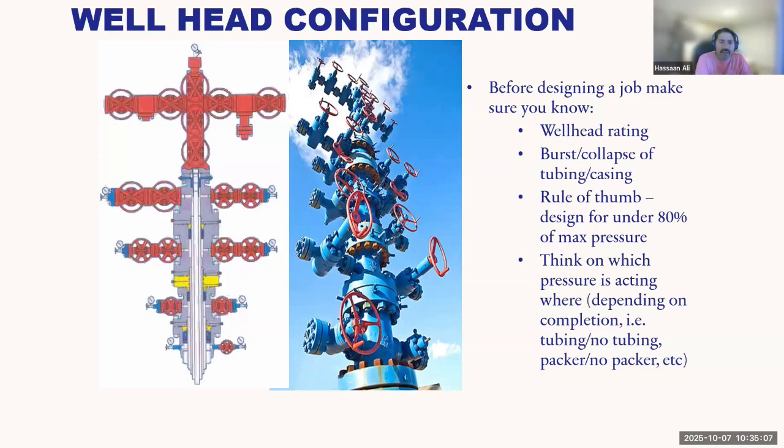So think of the wellhead as a means of production. It is right there on the surface. Some people call the parts in red, which you see right over here, a Christmas tree. Some people call it a production tree, depending upon the region and the area. It is called a production tree or a Christmas tree because it looks like a tree with branches. The tree is essentially a combination of valves and spools, which you can see right over here in the picture as well.